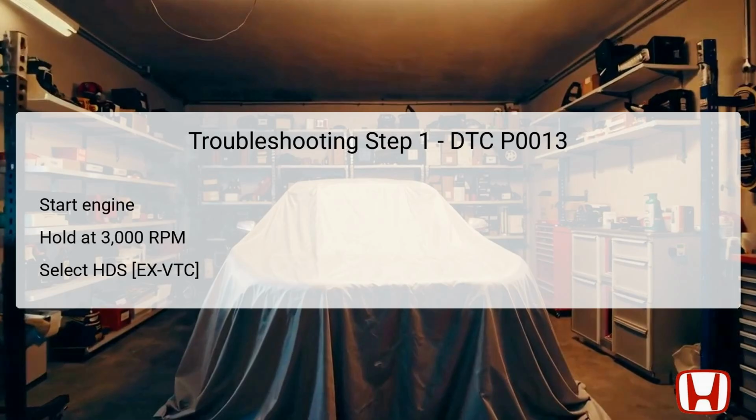Once the engine reaches this RPM and stabilizes, the next task is to select the appropriate diagnostic tool, referred to as HDS, which stands for Honda Diagnostic System, and then navigate to the EXVTC setting. This step is critical for retrieving the data and performing function tests on the VTC system to proceed with further diagnostics.